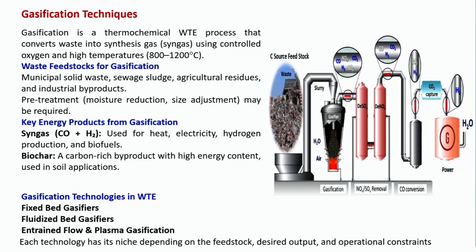This temperature requirement is very important, particularly whenever we talk about gasification. At the same time, that controlled air is also very important. Two things are very important with reference to gasification: one is temperature, another is controlled air or absence of oxygen.